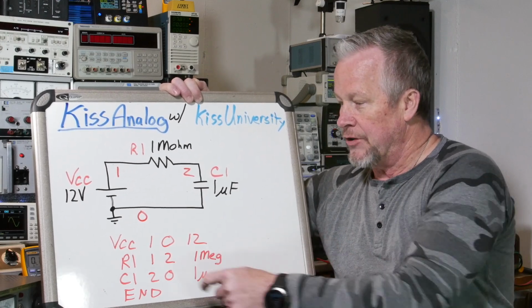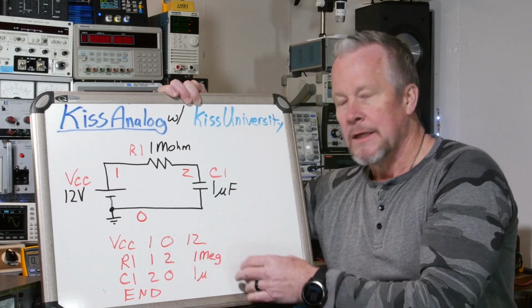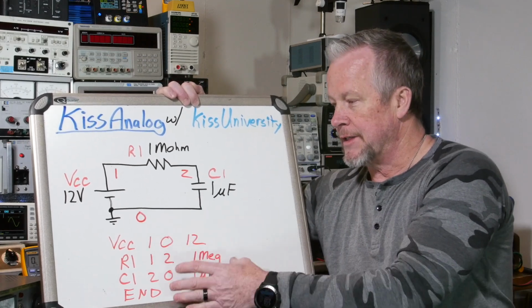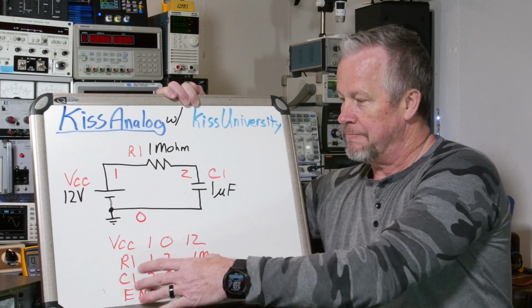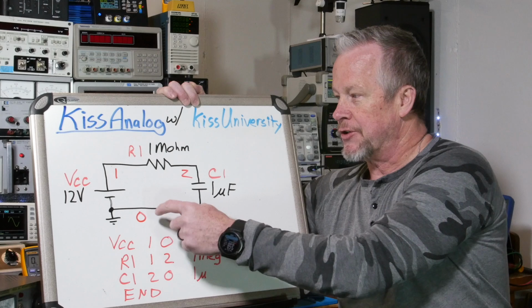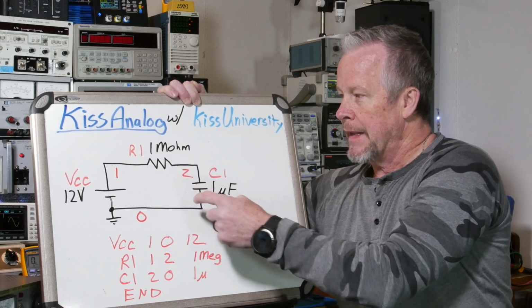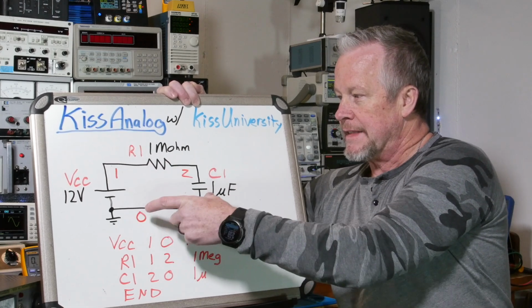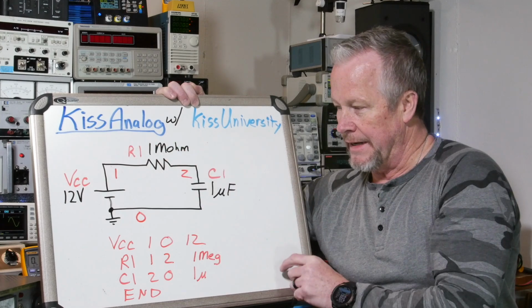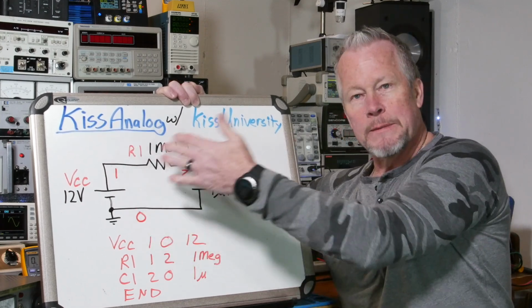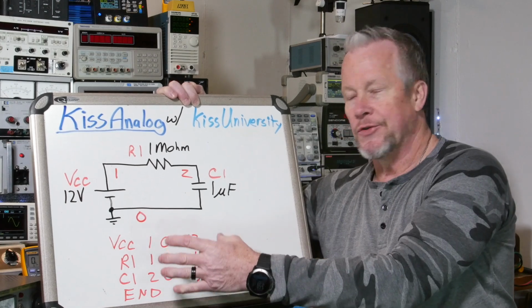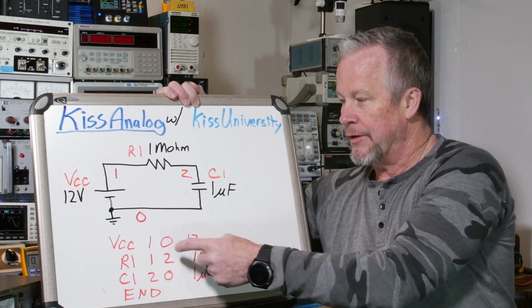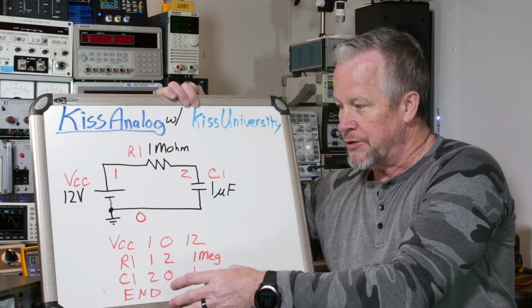Then after that, you have to write down your circuit. So then you would draw a list of your schematic in a nodal list, and it would look something like this. These are your nodes, okay? And each one of these is a branch, and you have your elements connected to your branches. And so you'd write them down into like a program list, and you'd follow the syntax for each one of these things.